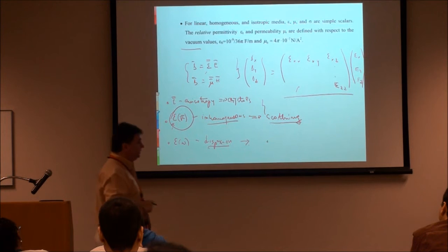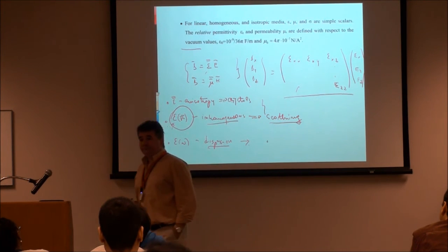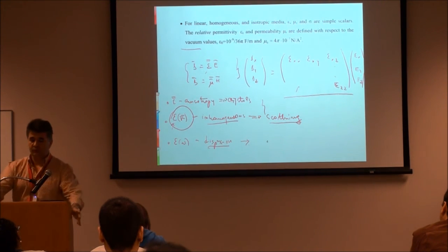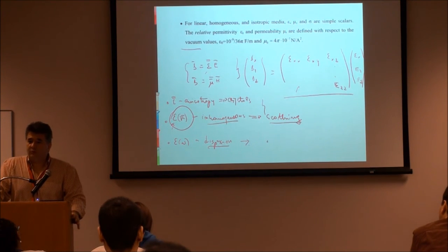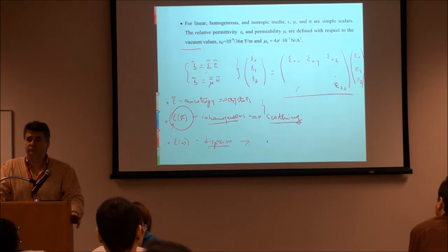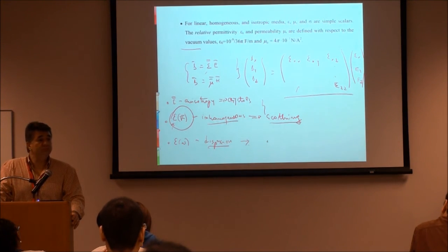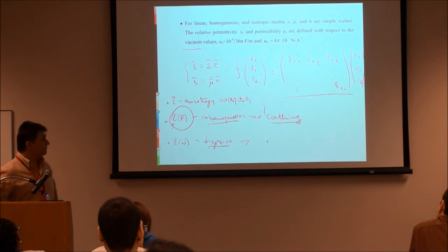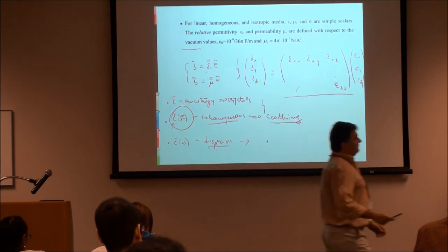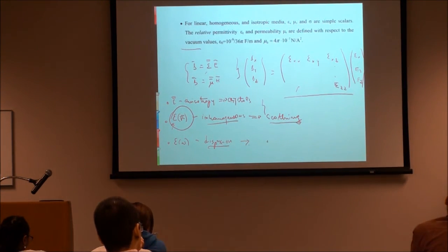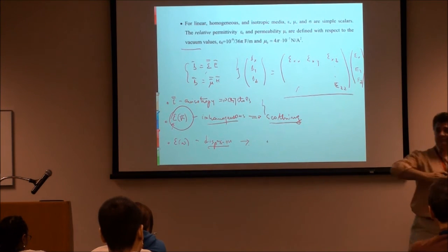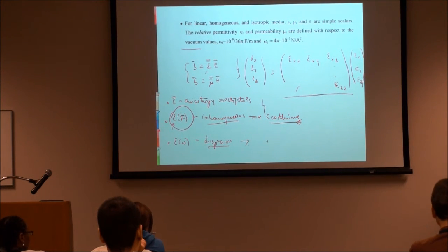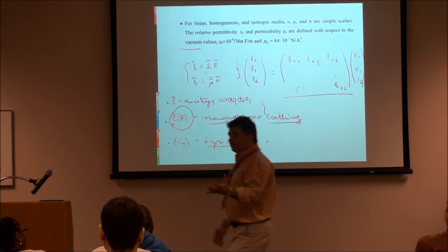Now, where is that useful in imaging? First of all, let me ask you in the time domain. Why is dispersion important in the time domain? What can that do? Pulse spreading. Even if I start with a very tiny pulse, what I get on the other end is a spread out pulse. And believe it or not, this spreading comes from the fact that H is a function of omega, due to dispersion. So can you think of an example where that's crucial?